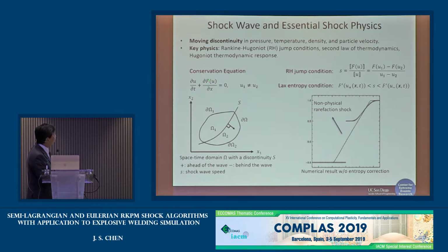Right, so when you have F being 1/2 of U squared, you take a derivative in x, and it will give you u times u comma x. So this is a first-order wave equation, but with the wave speed being not a constant, but being u, right? So the wave speed is a function of the solution. You can already imagine that it depends on the initial condition. If your initial condition in space is such that the value of u at a given point on the trailing side is higher than the u on the leading side, then the wave on the trailing side could catch up with the wave on the leading side and form a shock front. That's an easy way to understand why a shock forms.